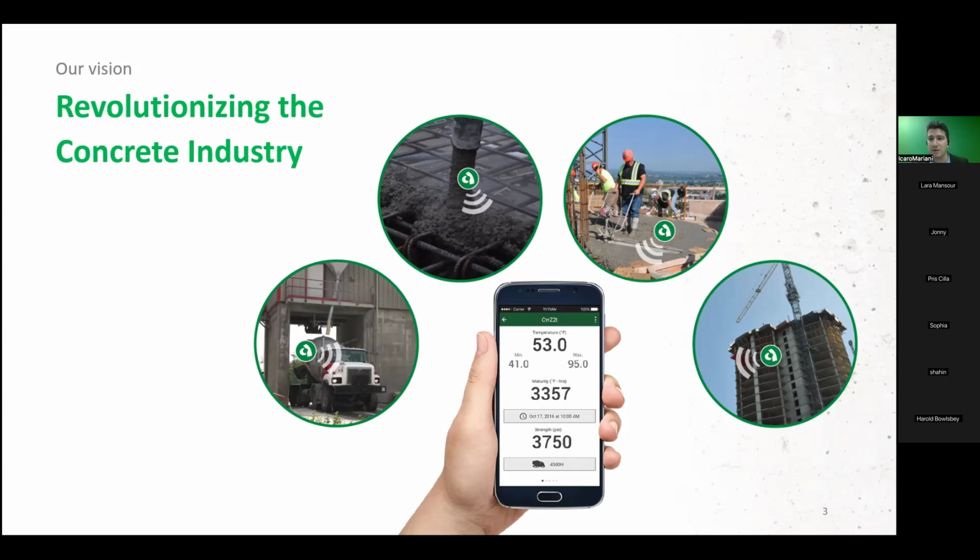So the first AI model we implemented was in the sensor itself, to identify a sudden change in the temperature. Let's say right now it's 50 degrees outside. Concrete comes at 70. That sudden change of temperature indicates, okay, that's my pouring time. But let's say it's spring and the concrete temperature and the ambient temperature are the same. We can actually identify that the hydration process is beginning now. So the algorithm behind it identifies, based on machine learning, that the correct pouring time is when the hydration process began. So that was our first model, I'd say, 6, 7 years ago.